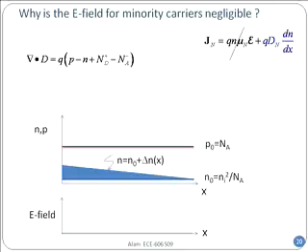There, my carrier concentration is no longer n naught. It is a little bit more than that, delta n, right? Now, in principle, then I cannot neglect the electric field, because I have a delta n, but it is not a photo-generated region, so I do not have a corresponding delta p here.